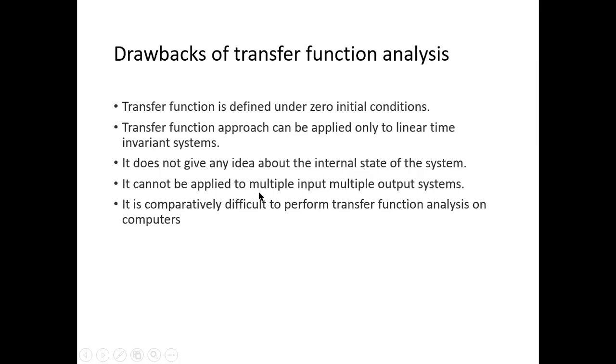The transfer function modeling cannot be applied to multiple input, multiple output systems, correct? And the state space modeling can. It is comparatively difficult to perform transfer function analysis on computers, correct? Because the S domain is there, and the calculation is not straightforward, as it is not any direct mathematical process, but the indirect way of solving the differential equations using the Laplace or the Z transform.